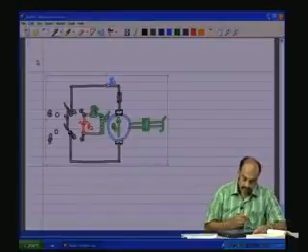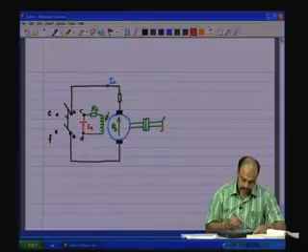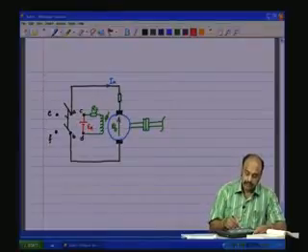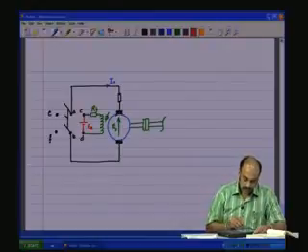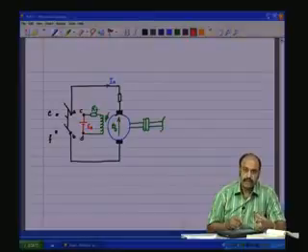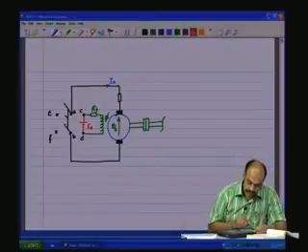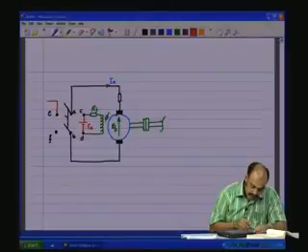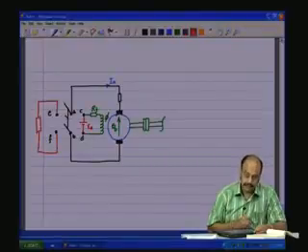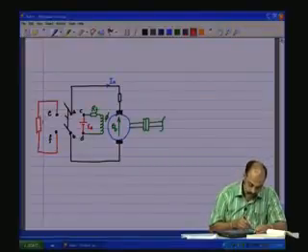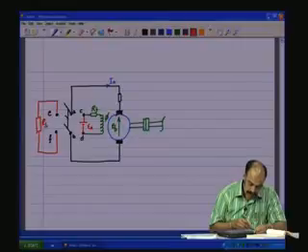So, in dynamic braking, what we do is, the energy stored in the inertia of the mechanical domain is going to get reflected as EB. It is a generator. Now, that EB, we will try to remove it by connecting a resistor here, let us say, RB.